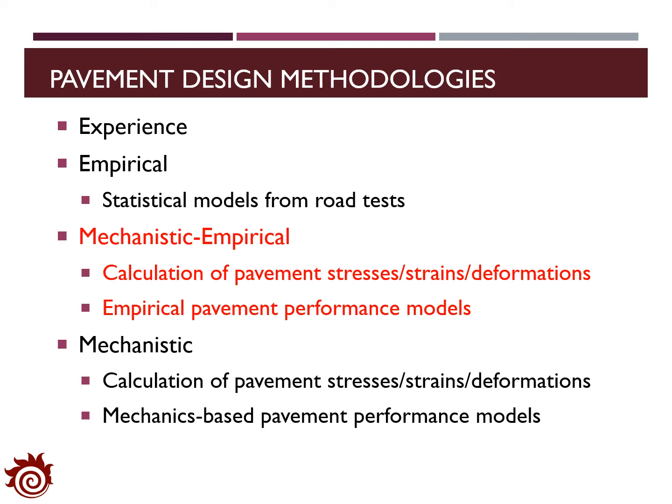In real-world implementation, there are a lot of methods to conduct the pavement design, but they can all be categorized into 4 types. The first one is the experience method. In this method, we will use our past experience to conduct the design. For example, if we want to design a parking lot, we can actually set a 6-inch granular subbase and then cover it with 2 to 3 inches of hot mix asphalt. And the depth selection actually comes from the past experience.